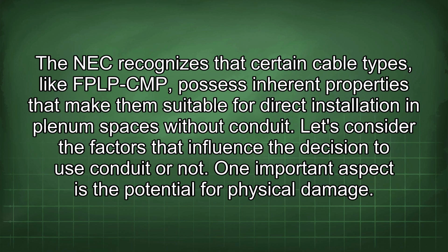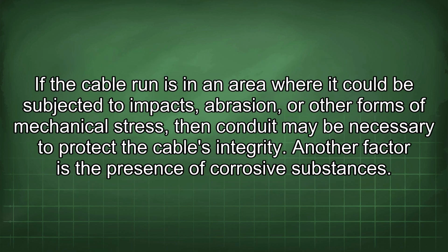Let's consider the factors that influence the decision to use conduit or not. One important aspect is the potential for physical damage. If the cable run is in an area where it could be subjected to impacts, abrasion, or other forms of mechanical stress, then conduit may be necessary to protect the cable's integrity.